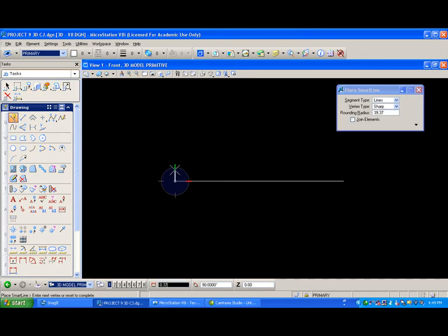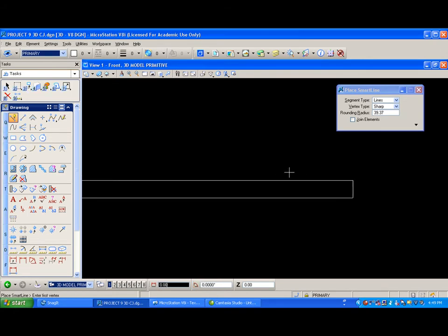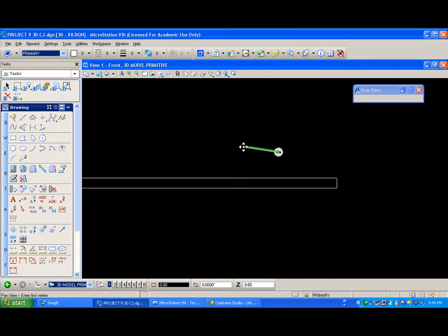We're going to take our Smart Line tool and draw this. This is going to be 3/16 of an inch thick. So I'm going to go with a vertical line, 3/16. I'm going to bring it all the way out to the end, hit enter, and then we'll close it down here. This is the outside edge where the tooth is going to be.